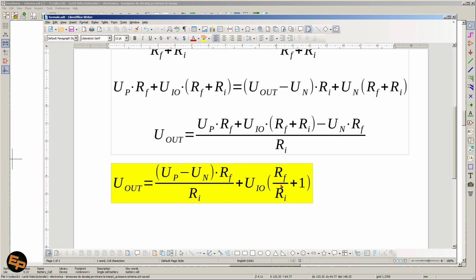And this is significant because for us this amplified input offset voltage is essentially an error, right? This error becomes significant, especially when we want to have high amplification factors like 100 or even 1000. 1 millivolt of input offset voltage is enough to cause 1 volt, plus or minus, on the output.